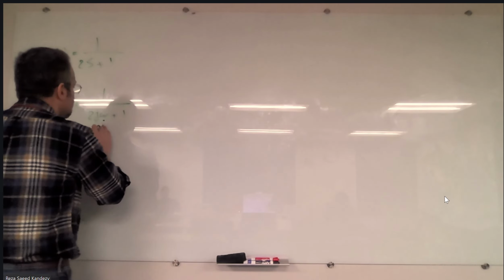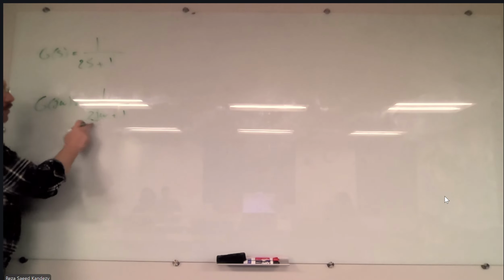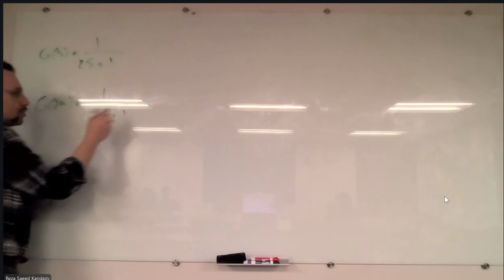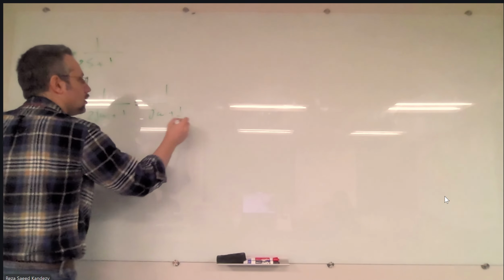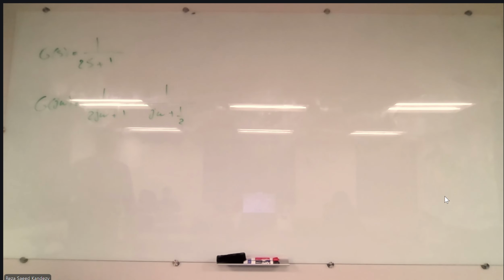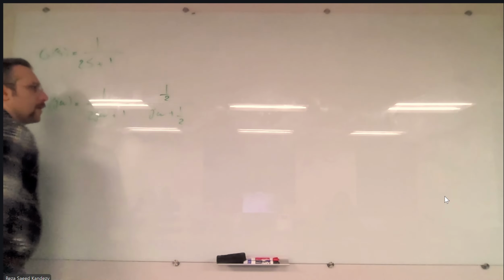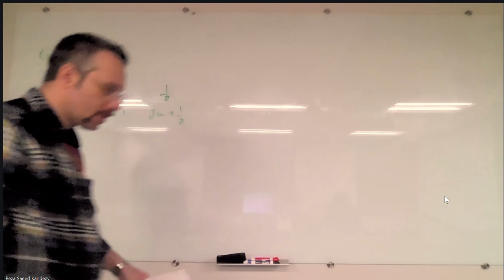Now, the next step for such an example is to make the transfer function in a standard form. What I mean is to eliminate whatever coefficients this omega has. So we are gonna write it as j omega plus 1 over 2. Are we good? So this is the same. Divided by 2, this one should also be divided by 2. Yes, the denominator is also 1 over 2.